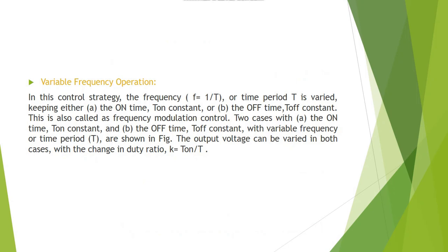In the first case we get 33.33 volt. In the second case, with the 1/4 ratio, we get 25 volt. So we can easily see that the value of the duty cycle affects the output voltage of these two converters, either boost or buck.